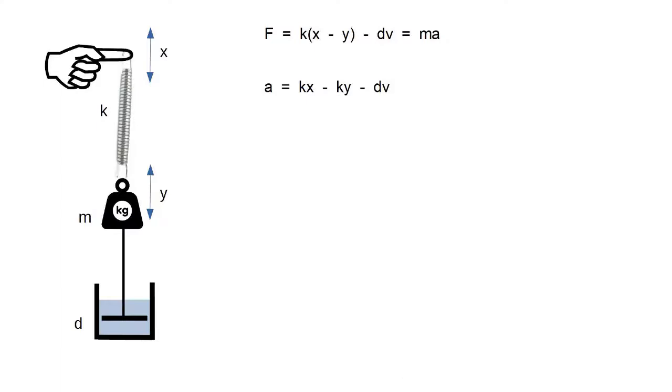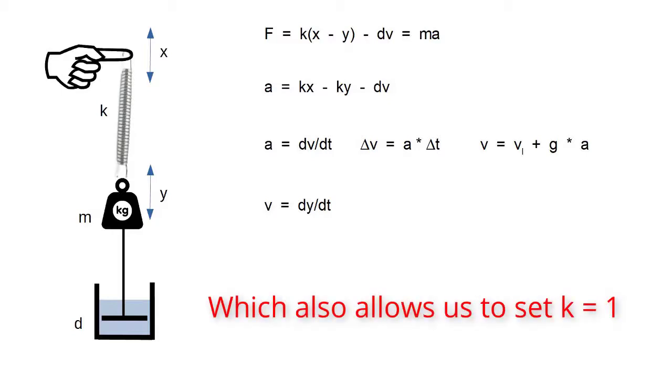Now a bit of maths. Acceleration is the rate of change of velocity, and velocity is the rate of change of position. But since we are sampling, one sample is the smallest unit of time we can consider. So the change of velocity between one sample and the next is the acceleration times the sample time. Now it turns out we could actually make this change in velocity the acceleration multiplied by a gain factor, and conveniently the cutoff frequency of the filter is then proportional to this gain factor.